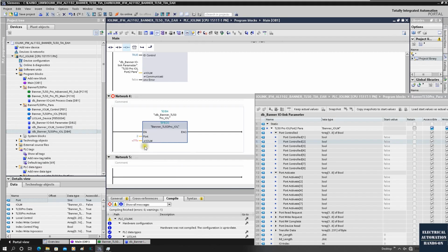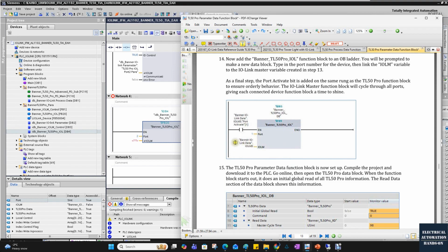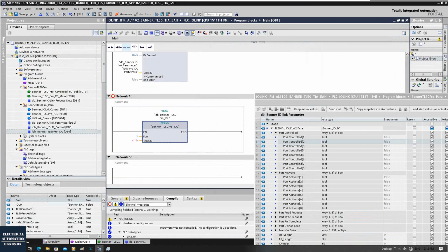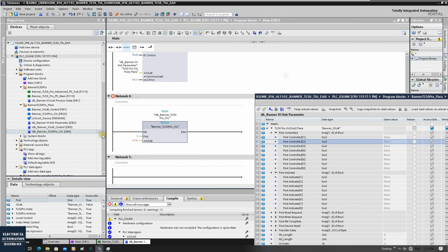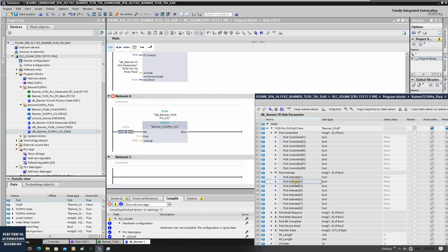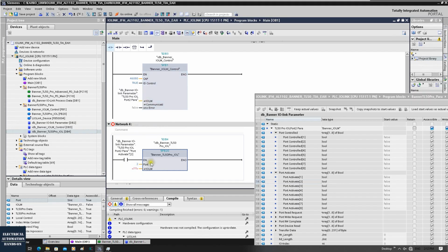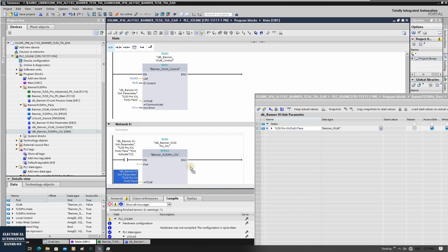Then what does this mean? We will see this function block also needs to use this DB. Meanwhile, when it's enabled, we can use this active signal. If we slide away, we will see that when it's enabled, it will use this port 2 active number 2. So this function block will collaborate together. That's why it's in and out here. Once active 2 is active, the port is active and matching with this port number, so it's operating this DB. We'll also drag this one to here.